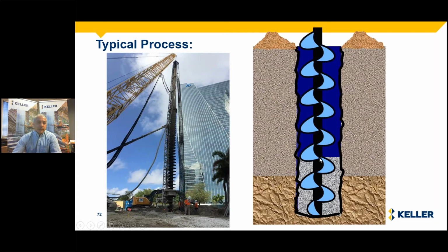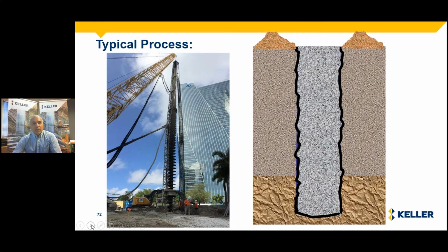5 feet, call it 2 meters, 3 meters, 4 meters, to be able to compensate for that kind of lateral pressure. When that is the case, then removal of the auger is being done and additional grout is being provided through it, leaving the hole open and then completely stable through that equalized hydraulic pressure between the inside grout and the external soil.